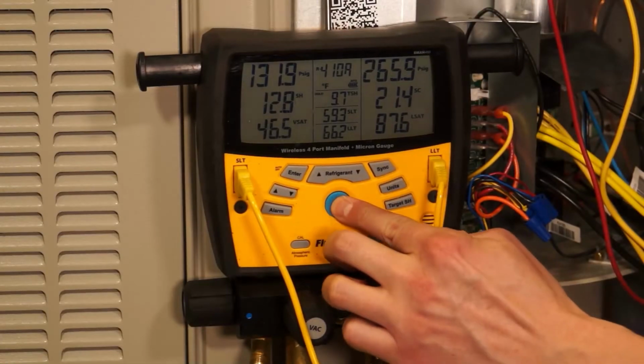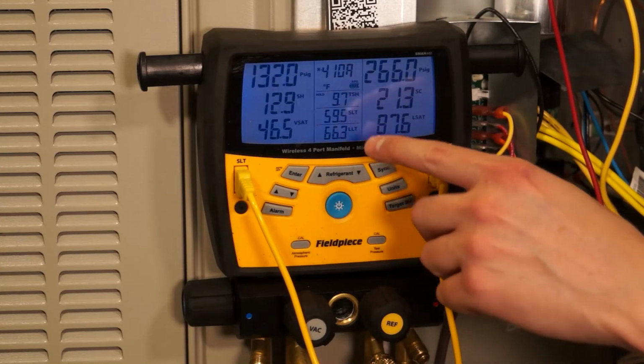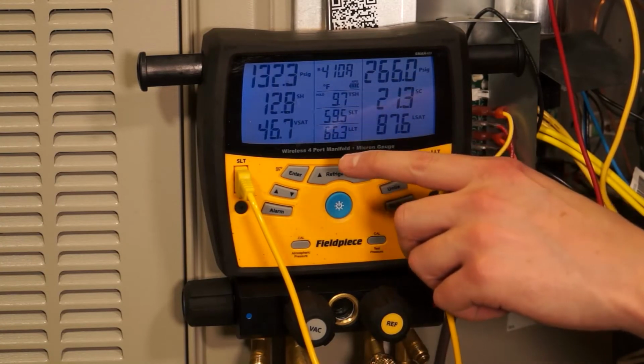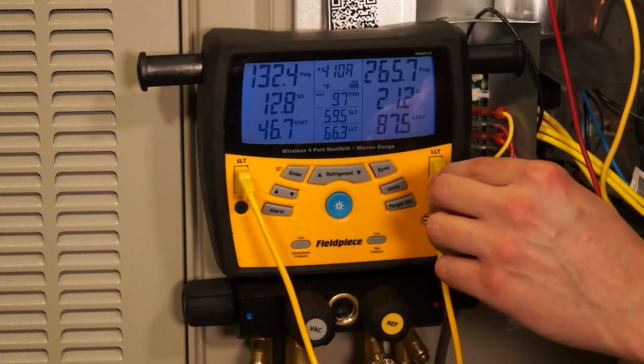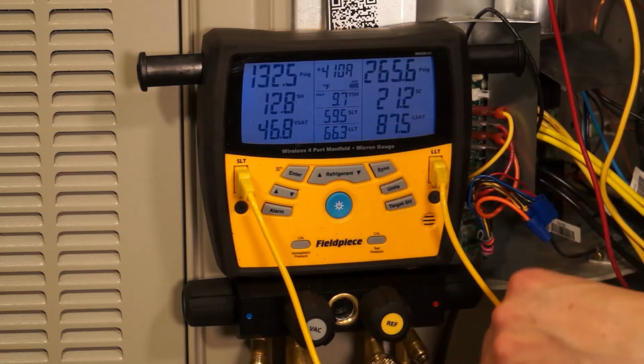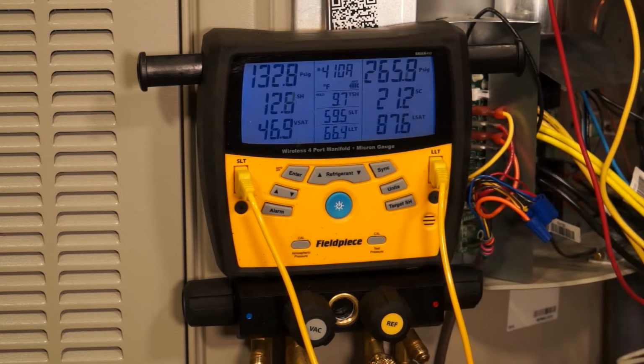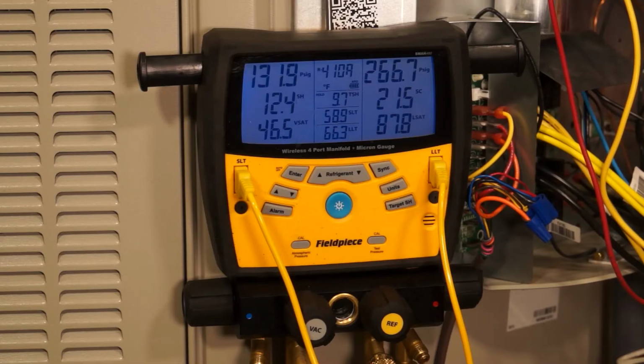So currently right now, what we're looking at is, let's call it 60 degrees on our suction line, and then on our liquid line temp line, we've got about 66. So we're within about that 7-degree range that we want to be at. It's a little bit cooler in this room, so our temperatures are a little bit farther away than what I would want. But basically, you want to be about 7 degrees on the differential on your reversing valve.